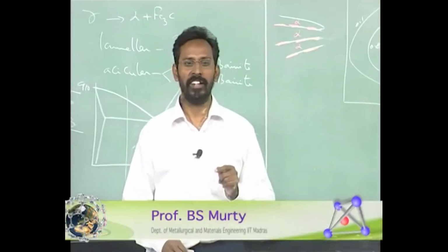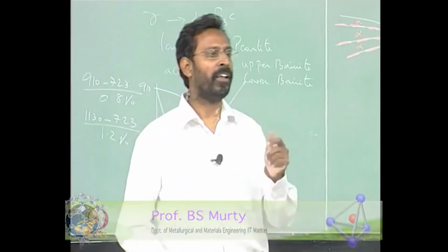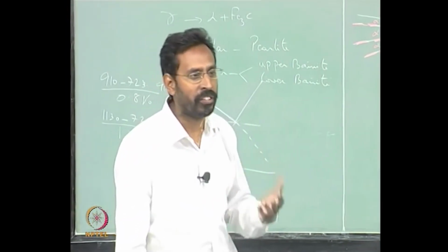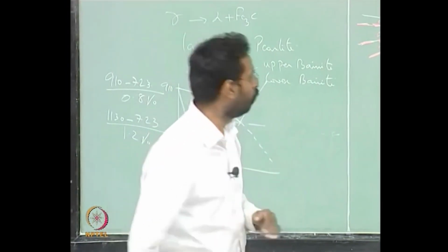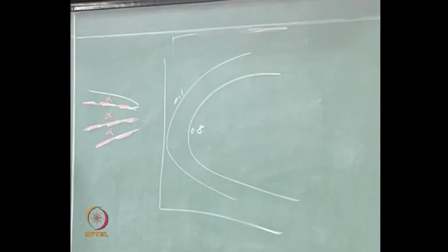What Sriram said is right, you do not see a significant shift, because whatever you lose because of one, you gain because of the second one. So you do not significantly see shifts, whereas you see significant shifts on the hypo side. That is something which you need to understand. If you do not understand that, you would not be able to understand the hardenability effects in different compositions, and this is very important.